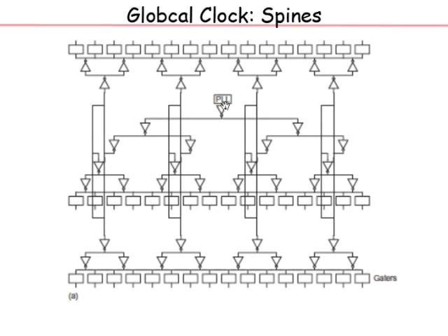Correct. So the important thing is from this PLL to the spines, the three spines, the delays will be the same. And that delay, distance need not be the same, delay will be the same. You see these buffer trees they have shown already, right? This is how they are buffering it. It's been done very carefully such that the delay from this to these three spines is the same.